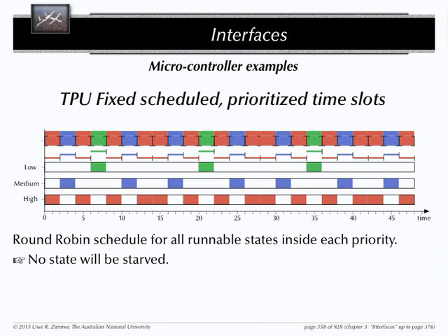So it's a weird crossover between what you will find in a Linux environment and what you will find in a hard real-time environment. Because you will not have in a real-time operating system any kind of a round-robin thing. But here you have a round-robin which is connected to specific priorities. So you can place your functions in different priority bands. And depending on the priority band, you will get access to the CPU in a certain pattern.